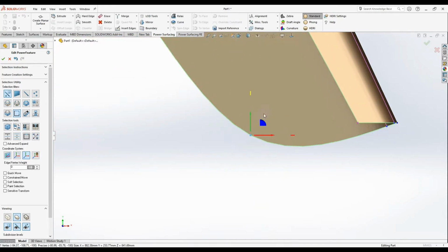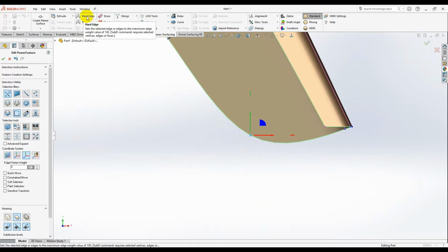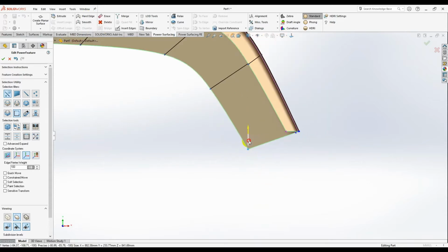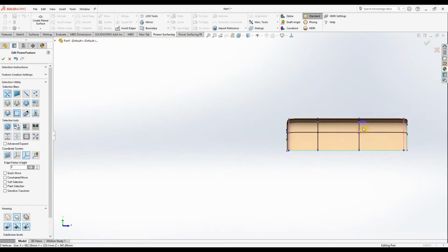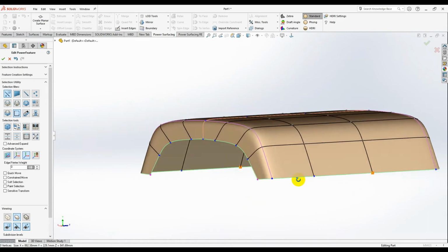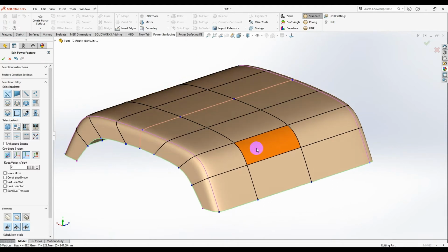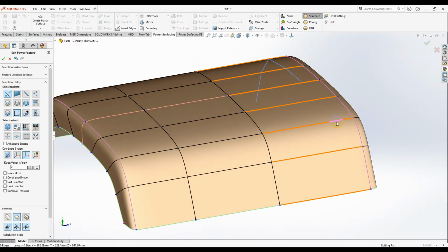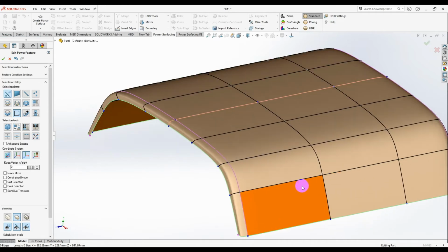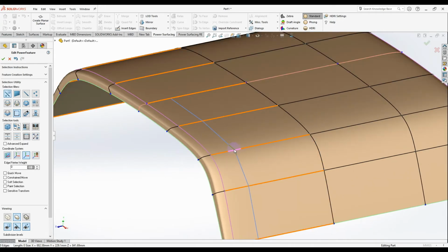We can use this point here again and click on the hard edge, and we can raise it a little bit to give this shape. Now we're working vertically with the movements. Okay, now I'm gonna increase the level of detailing. Let me first insert a loop from here. I'm gonna insert a loop by pressing and holding the A key and stopping at any line, and it's gonna insert a line wherever you want.